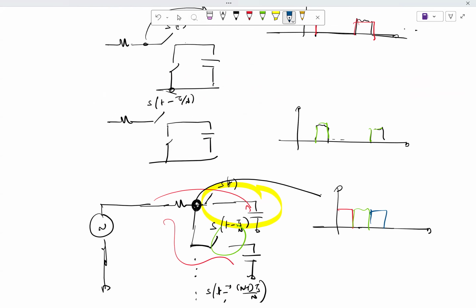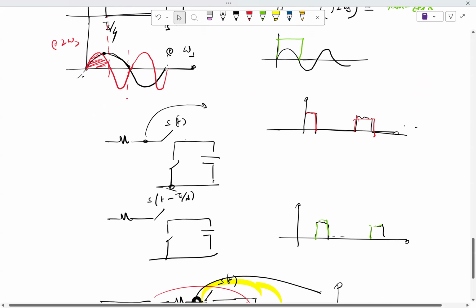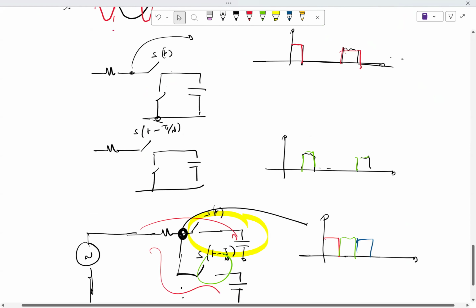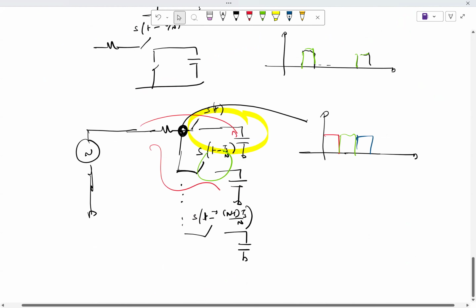So you are stacking them up just like you are doing here. Right? So even though the block diagram seemed complicated, in principle it's an extremely simple circuit. You have 1 R, 4 switches, 4 capacitors. Right? And because you have N phases and each phase has a path associated with it, these are called N-path circuits. And this does filtering, so hence it's called an N-path filter.